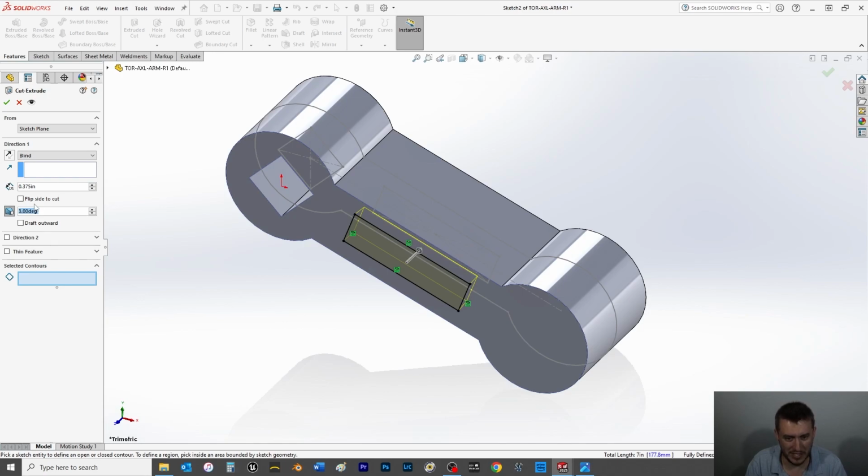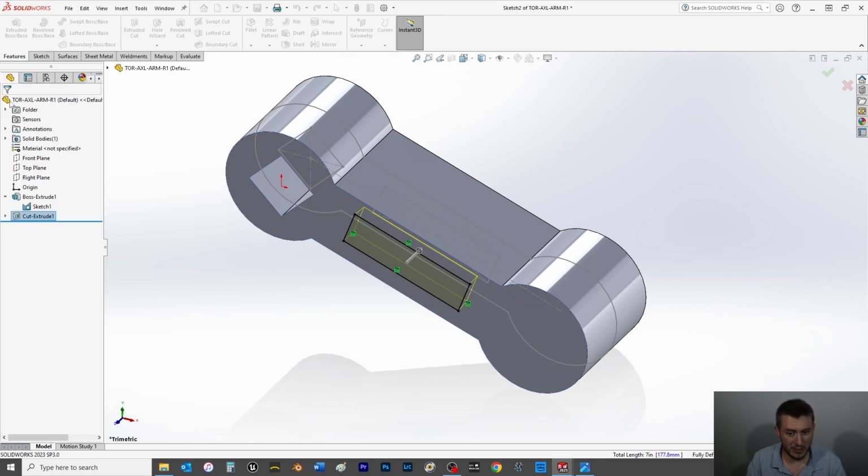I mean, it's not super deep, but again, I honestly have never worked with forged parts before, so I don't know if drafting rules necessarily even apply to forged parts versus cast parts. I work with casting parts, and oh yes, you've got to have draft angle. So, leave a comment below if you work with forged metal and forged parts, and if drafts are required, or if you can get away with a lot more. So, we've created the draft there, so we can select OK.